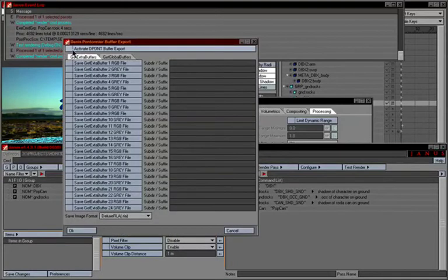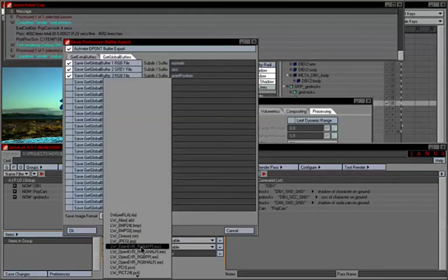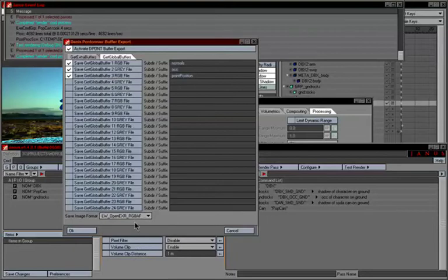and here I'll activate the buffer export, and you see two tabs, Get Extra Buffer and Get Global Buffers. Get Extra Buffer is shader or surface based, while Global Buffers is based off the pixel filter editor, and this is what we'll use. So I will check the RGB and the gray, those three buffers, and if you remember, normals is the first, occlusion is the second, and the third is the point position pass or the world spot. Now at the bottom here, I'm going to select OpenEXR, because I want a float FP format, especially for my normals and for my point position pass. It's quite important to have that.